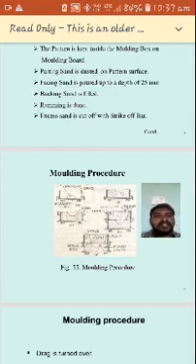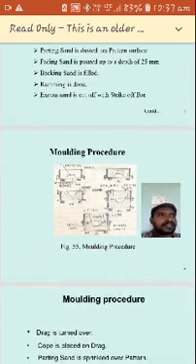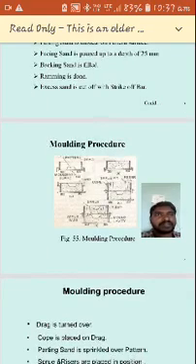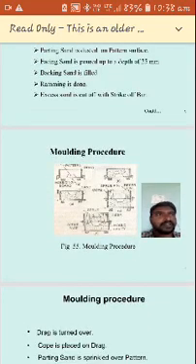After filling the surface, we use backing sand. After placing the facing sand we go for the backing sand, and then we go for ramming. We take the rammer and ram the sand, including the corners. Due to the ramming, the sand particles stick to each other and become stronger. That is why we go for the ramming option.